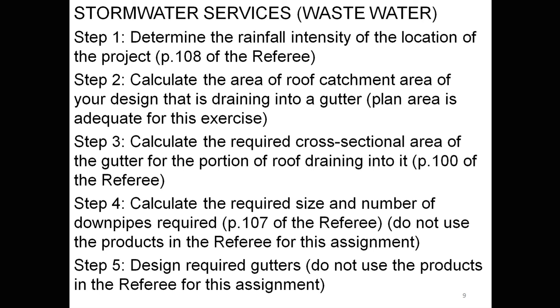And the other thing is, it comes down to function. When I was talking before, we ended up with a box gutter that was 167 by 167. That's for a roof area of 400. That's a really convenient size to get your foot stuck in. So what I'd be much happier with is to make the box gutter wide enough so that one can actually walk in it. So you make it 600 wide, and then it can be a lot shallower. If you don't need it to be a lot shallower, you just keep the standard depth and just make it wider.